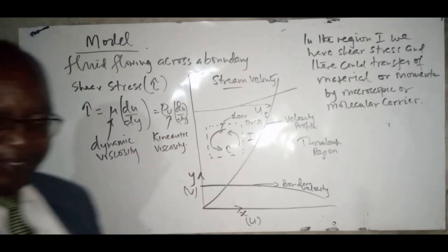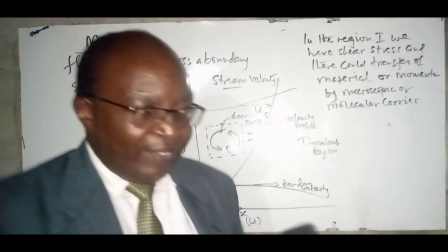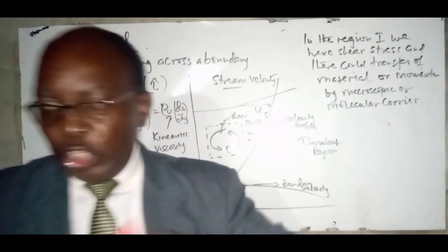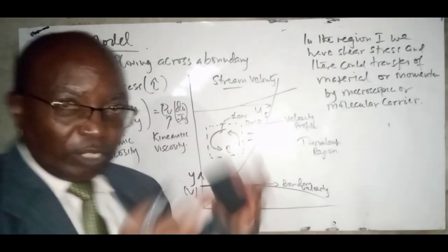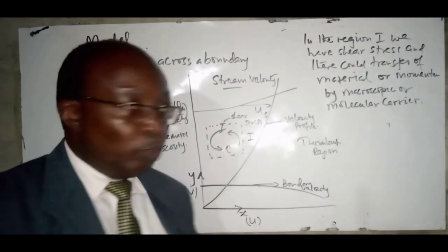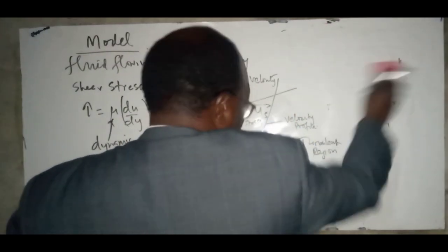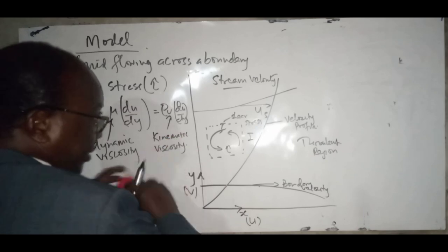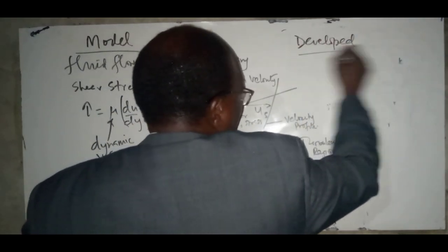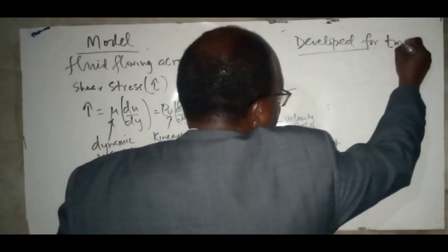Viscosity. And so when we developed the concept of the turbulent boundary layer, we developed expressions which related the shear stress due to turbulence, so that the total shear stress was the shear stress due to viscous forces and also due to eddy shear stress. So let us just, so we developed the turbulent region,